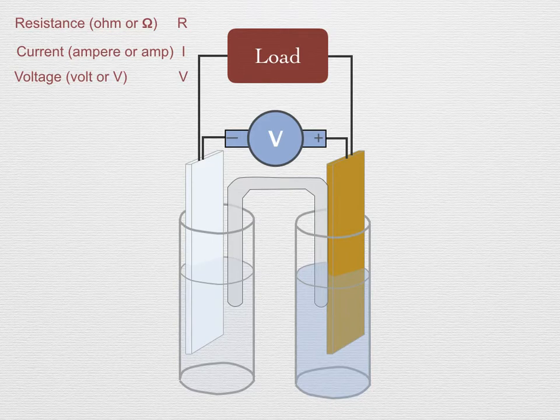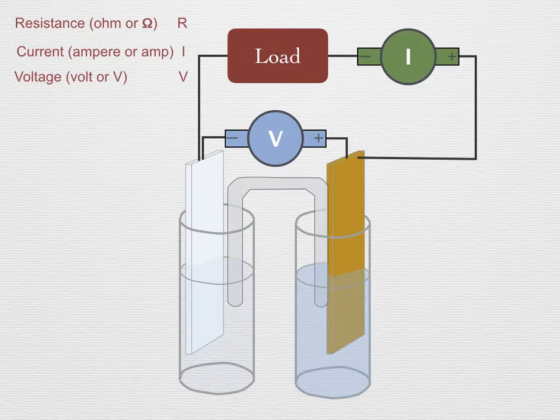If the internal resistance of the cell is small by comparison, then the voltage can also be attributed to the cell. We measure that current with an ammeter placed into the circuit. An ammeter is a low impedance device, meaning that it has very little resistance and does not add appreciably to the current being drawn. With a voltmeter across the electrodes of a cell and an ammeter anywhere in the external circuit, these devices can together measure the voltage and current in the cell and provide the information we need about it.